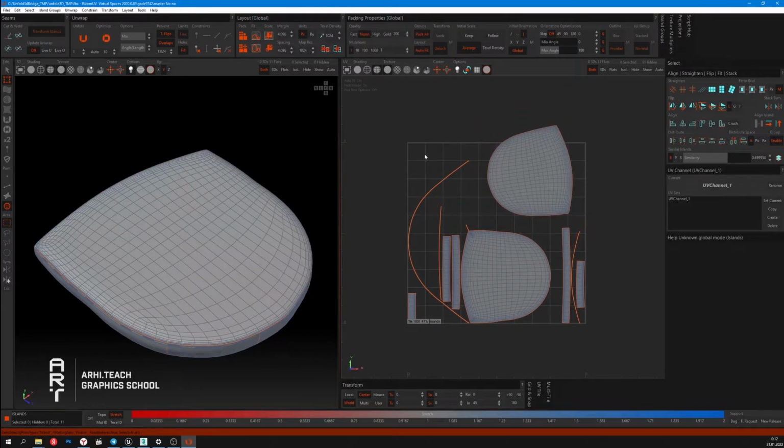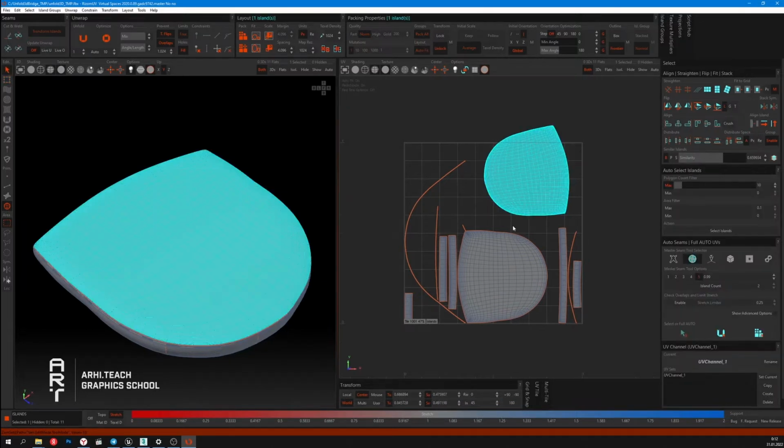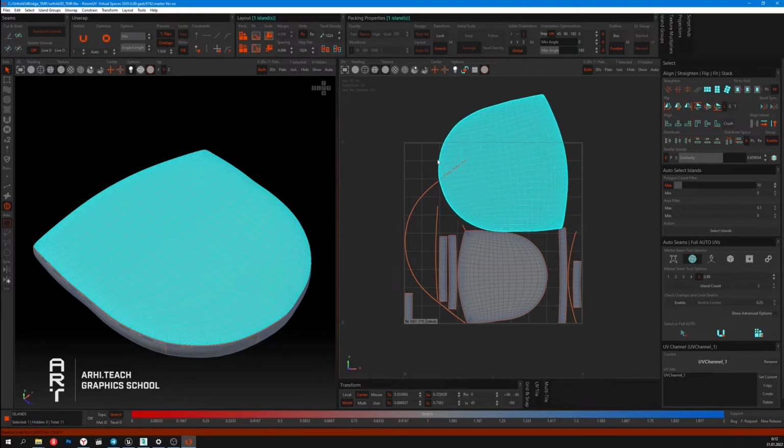This tool also has a hotkey. It's the F5 key. The Tab key is also really easy to use. The Tab key does a tool call without the need to switch to it. When we release the Tab key, the Transform tool actions disappear. We need to use Shift with this tool in order to scale the unwrap on the chosen axis.